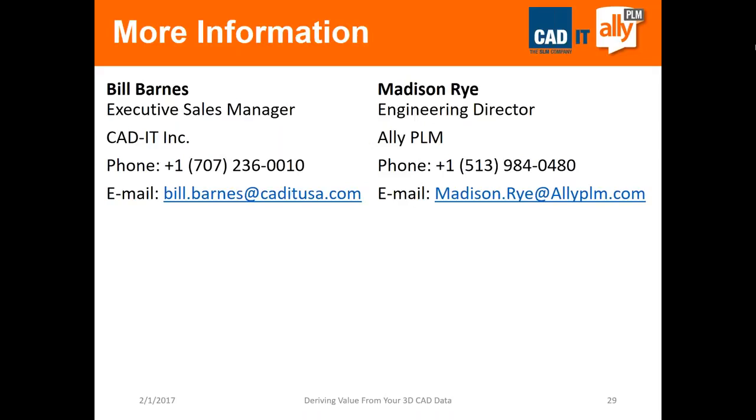If you're driving it from SAP PLM, you can launch the application, but the Team Center connector we have will give you a whole host of things that you can control from Team Center. With SAP, it's more of passing the data and the bill of materials to the application, and that would need to be configured. But it's possible to utilize other PLM environments, though we only have the connector available for Team Center.